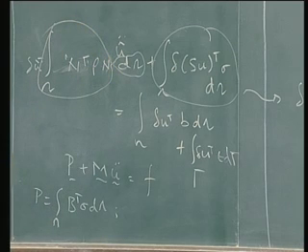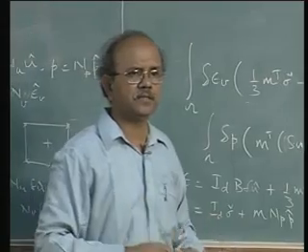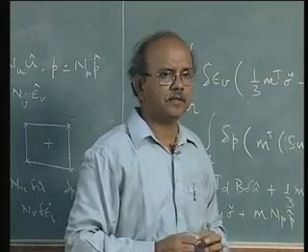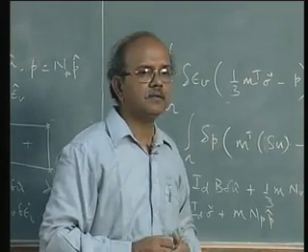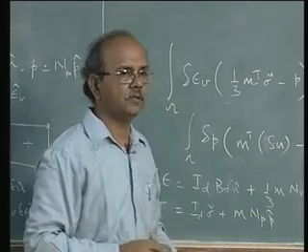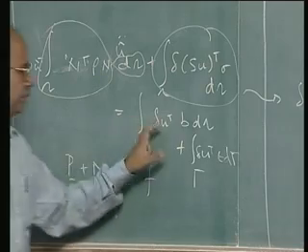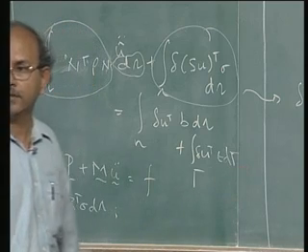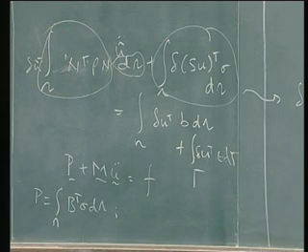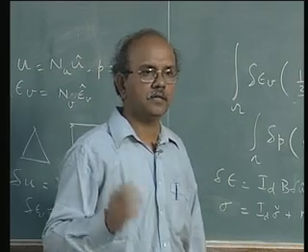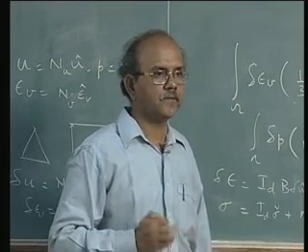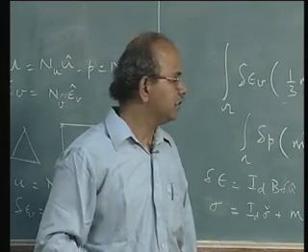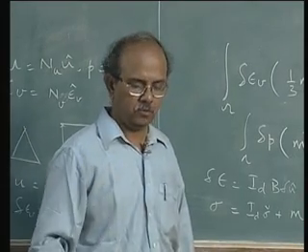M is rho N transpose N d omega, your regular M, nothing has happened to it, right, is equal to F. F consists of these two terms. This will become N transpose b d omega, N transpose t d gamma, the two terms for the external forces F. So the first equation is the same, there is no change in it.